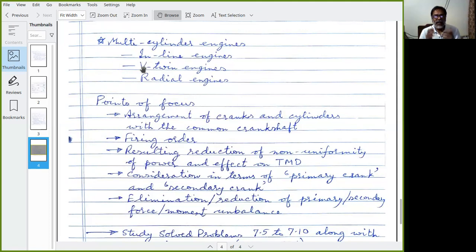But then, compared to having a single cylinder engine with a particular capacity, which means a particular unbalance, if you split it into two smaller cylinders, two correspondingly less power-giving piston cylinder alignments, such that their unbalances partly balance and partly sum up together, that is a relative advantage. So that is the advantage a V2 engine gets.